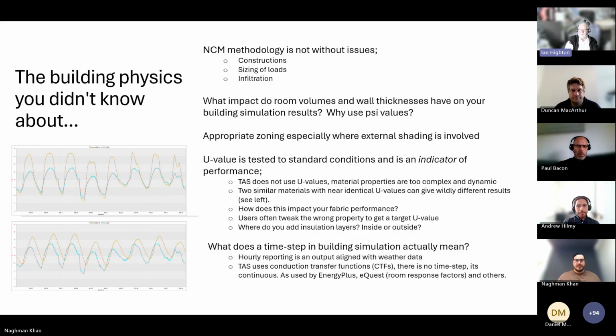So you're looking at a line that's mostly center line in terms of the wall, and we work from those values, which means we obviously increase the internal surface areas, which is what a lot of packages work from and why they need the psi values. But we're effectively doing this geometrically, which I prefer, because psi values are fixed, per linear meter of perimeter, whereas what we're doing is saying, if you change your thicknesses, you're actually going to see the edge losses and the thermal bridging taken account of automatically, which I think is a better way of doing things.